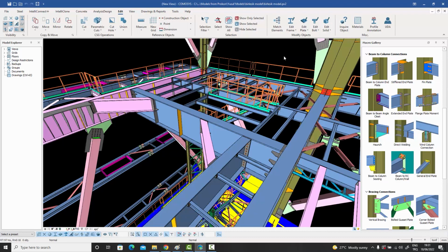And if you need to go and enter all these numbers every single time you're using the macros, that's how it adds up, because you don't use them once, you use them thousands and thousands of times again and again. And not only do you end up losing time, you also end up creating an inconsistent model. So my advice would be to please set up this project preferences file immediately when you start using Comosys. Set up your angle gauge distances. I mean, in all probability, the default values will be fine. But if they're not, and if you want them modified according to your own country, then set them up, and then just basically forget about all this and just start using the program.